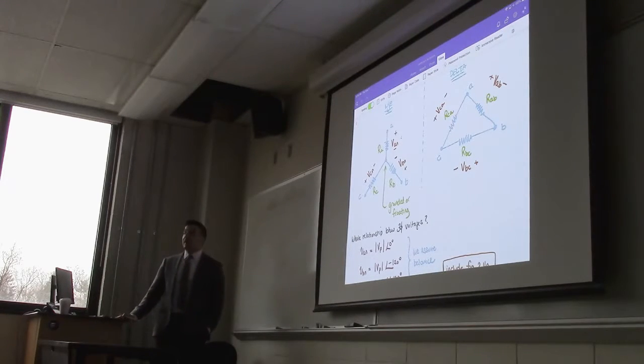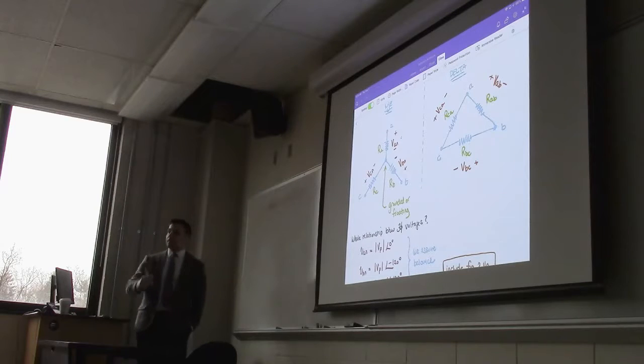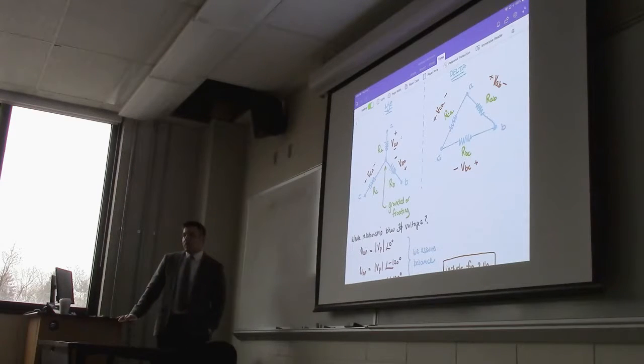So when we balance the system out, what we're trying to do is say, okay, 5 classrooms will be on phase A, 5 classrooms will be on phase B. Aren't some sockets, like a washer and dryer, different? Yeah, there are also 30 amp plugs. So a 30 amp plug would be two phase. I never thought about that. That must be delta connected to get the maximum voltage between the phases.